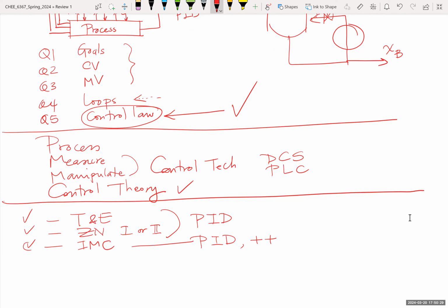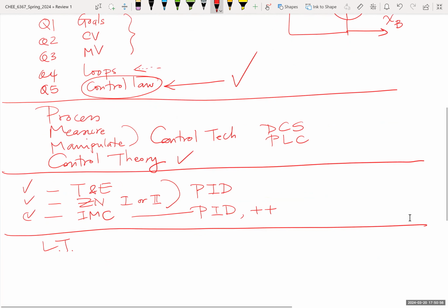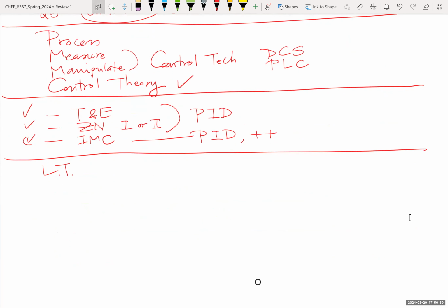The tools, the control theory that you need to apply this and understand this, are a few things that are important to understand, although you do calculations by hand all the time, but it's more to understand how these calculations are done. And one fundamental element is Laplace transforms. Laplace transform is a dreaded topic, and one should perhaps abandon the name so that the fear factor can disappear. Because in essence, all that this does is help you do algebra rather than calculus with dynamic systems.